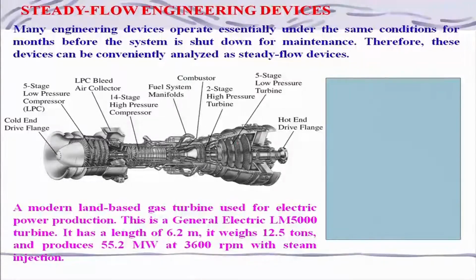Now, when we apply this energy equation, we have looked at the kinetic energy term. Let us look at whether we can neglect the change in velocity or not. Kinetic energy goes by the square of velocity. If the velocity change is low, that change will be negligibly small, whereas the higher the velocity, the larger it will be.